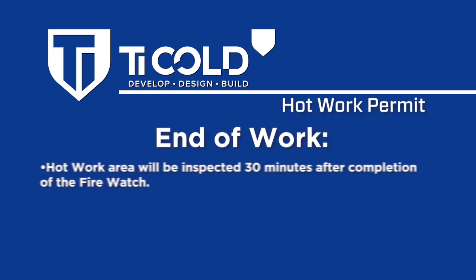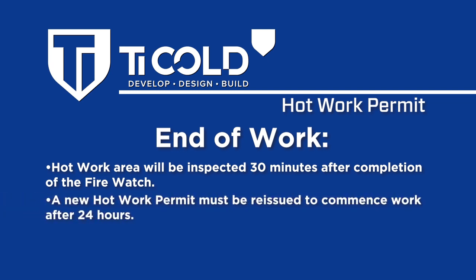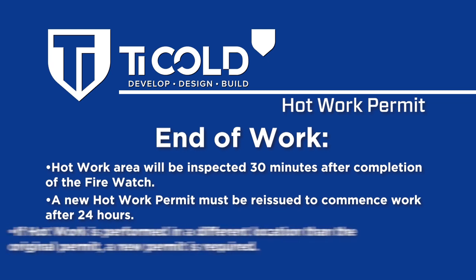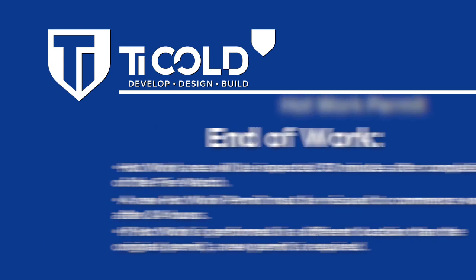End of work. Hot work area will be inspected 30 minutes after completion of the fire watch. A new hot work permit must be reissued to commence work after 24 hours. If hot work is performed in a different location than the original permit, a new permit is required.